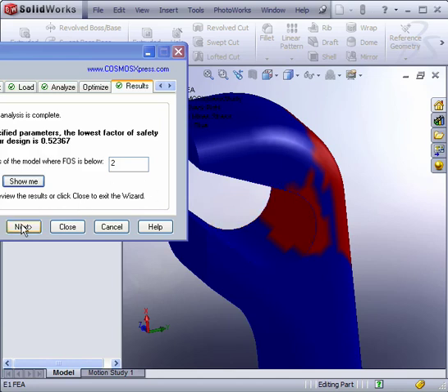And that's where nonlinear analysis comes into play, because as you would realize, the more it bends repetitively, the more it weakens. And linear analysis, which we're doing right now, is only good for really one shot. Nonlinear will give you the results for many shots. So if it keeps bending, how is it going to eventually fail? It's going to weaken every time, and it's going to be weaker and weaker every time you use it. That's why that analysis is much more thorough. But like I said, 90% of the engineers out there use this.